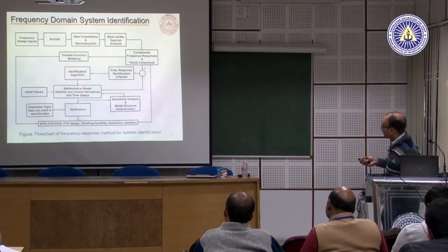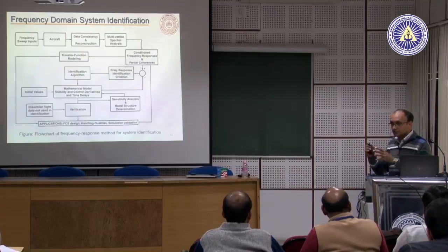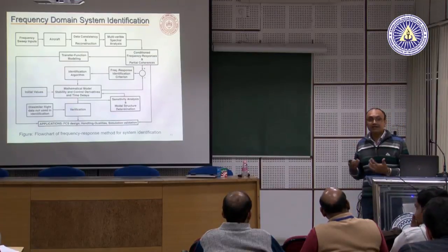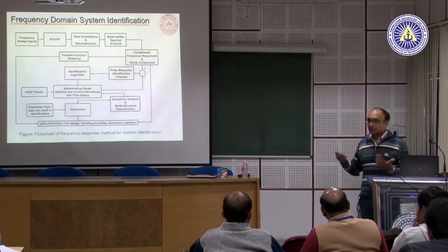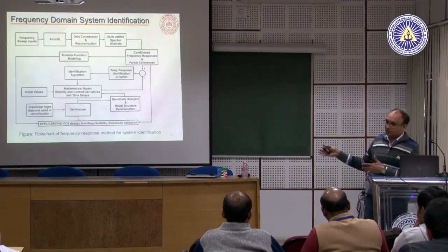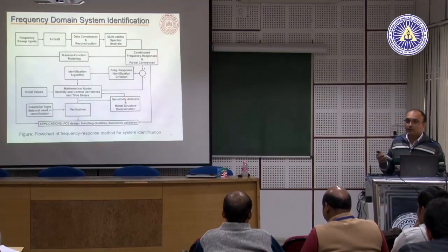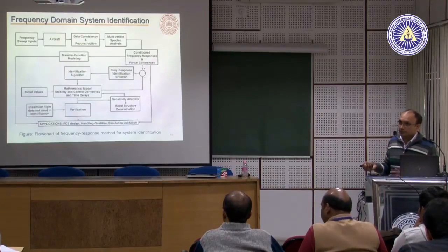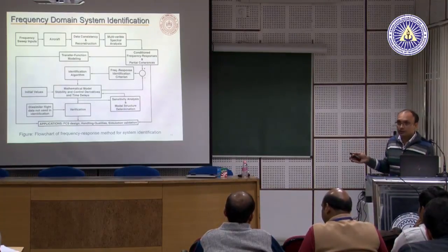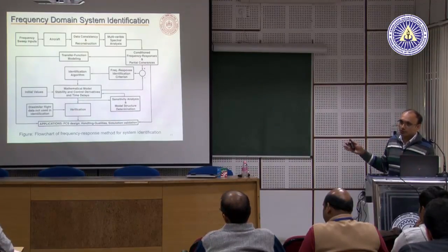Once the model has been identified for a multi-input multi-output system, now to identify this also you may have to specify some initial guess values, because this estimation or this identification actually happens in an iterative manner, right. So it is not magic, okay, it will not automatically populate all the values. We have to start with a known model or a known structure for the model, and then we have to give some guess for those numbers. So like all those parameters we saw, all the control derivatives and stability derivatives, we would have to give some guess value to start the whole process.